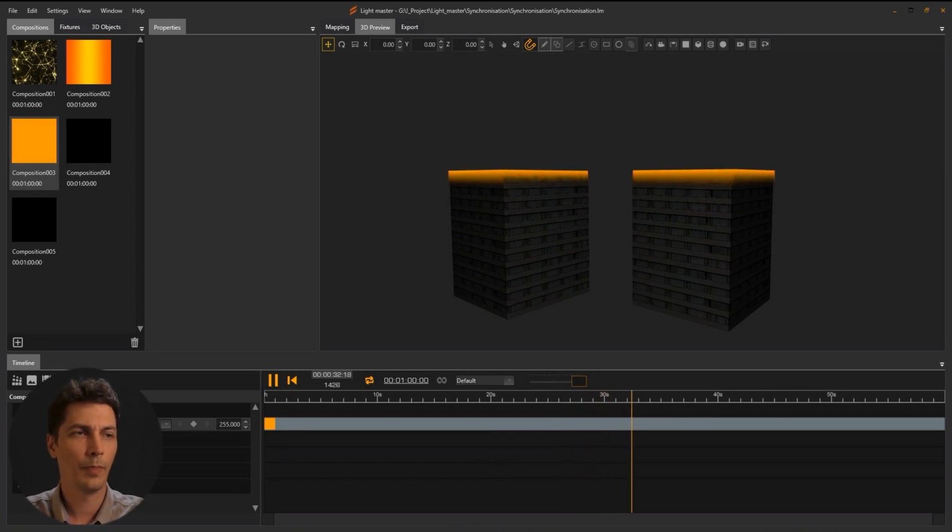The output of the Light Master player is ArtNet, and then we will require a converter to convert the ArtNet signal to DMX or SPI. In my particular circumstance, it is DMX. Due to the small quantity of lighting fixtures, I will need one device assigned for every individual building in the vicinity.